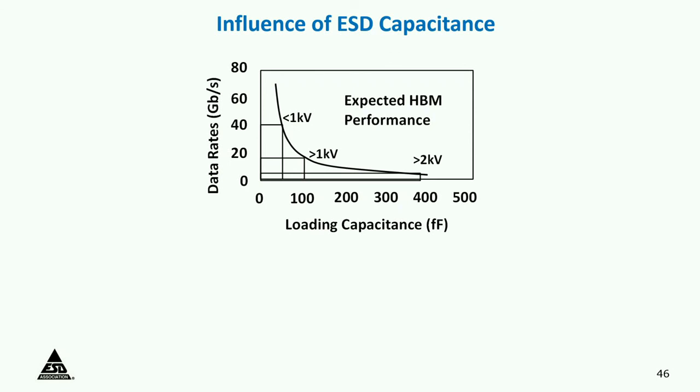But for the next few years, it is going to be such a serious thing that the ESD Association is trying to approach DoD for some funding to understand how to deal with it, especially now that we are getting into more 3D ICs, gallium arsenide devices, gallium nitride especially. These devices break down at a couple of hundred volts. That's the only protection they have, and they get easily damaged. You cannot build ESD devices out of these technologies.